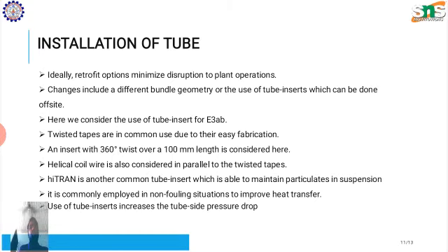Divert all crude flow rates to E3AB after the flush. The exchanger E4 has the smallest duty in the network. If there is sufficient cooling water duty available to cool stream 4, the diversion of crude to E3AB will further increase the wall shear stress to reduce the fouling in the long term, and the pre-desalters also.